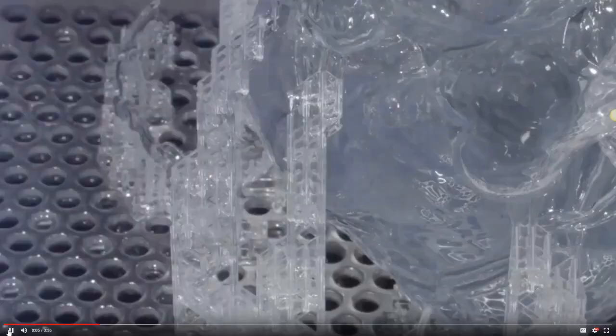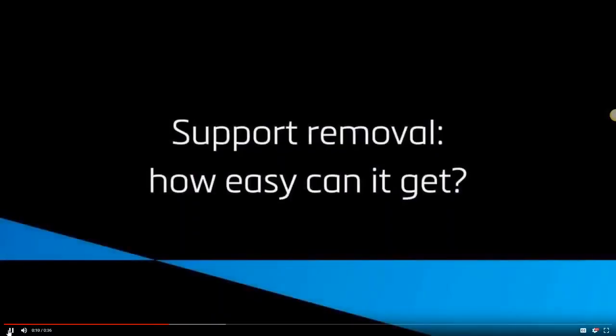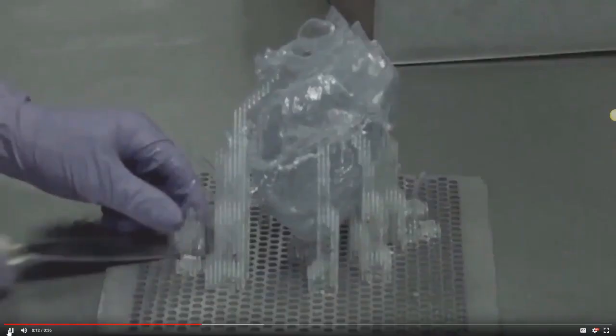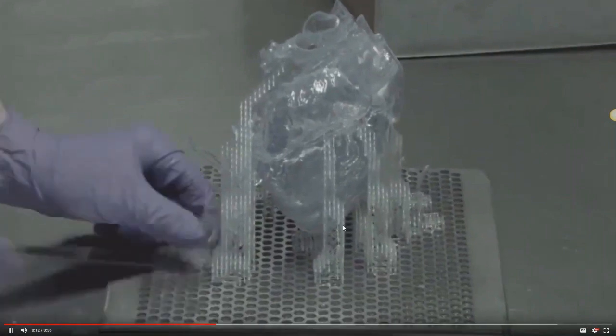So when you're done building, that's what it looks like when it raises the part out of the resin. And so this is what you do when it's done printing. You need to wear gloves because the resin is something that's a hazardous material. So you always want to use some gloves, but you can see these supports are really interesting. They're made to build away from the part, so it cuts down on your post-processing time, and they just kind of break away.